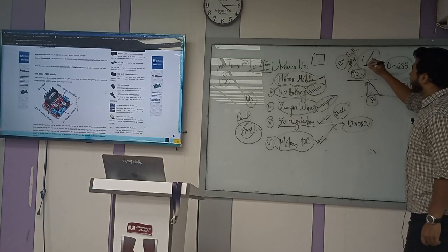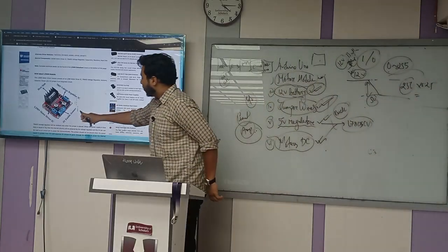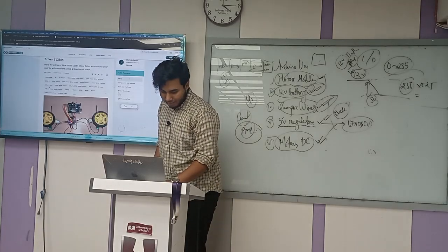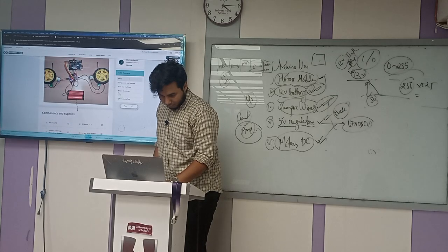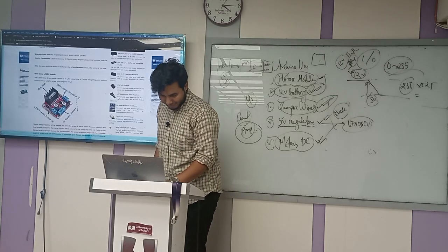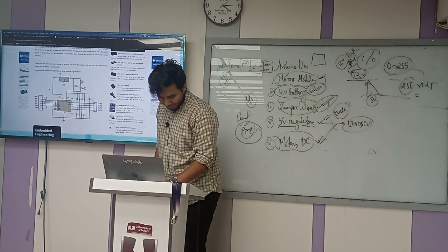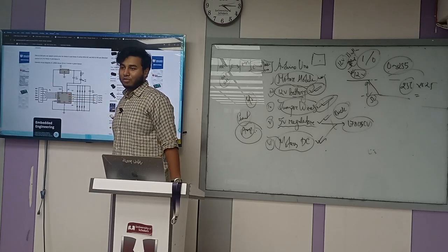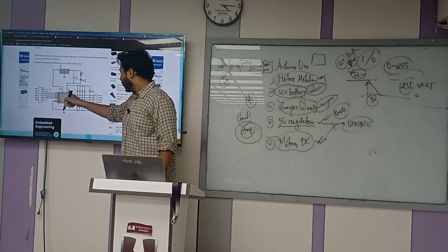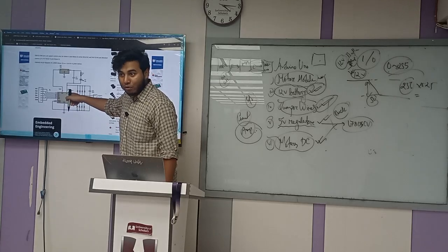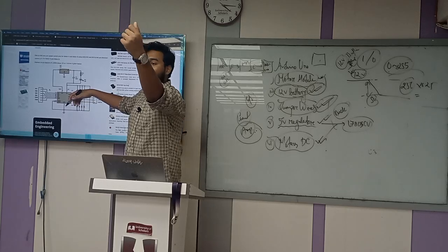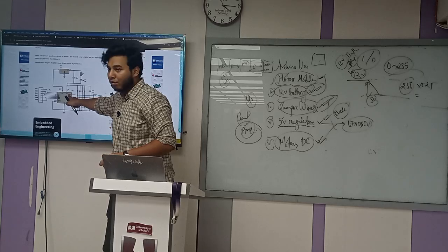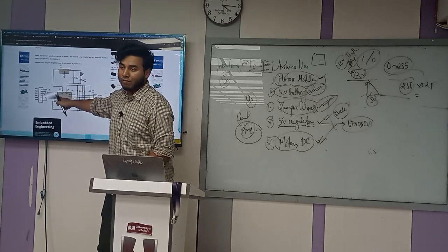And whenever you are going to connect this motor driver, the 12-volt connection, what is the fun fact? This is the main diagram. This module needs 12 volt. There is an extra pin of 5 volt over there. It is the output, not the input. So if you have something like an LED, a buzzer, or a sensor, you can work with this 5 volt, but I recommend you not to use this 5 volt.